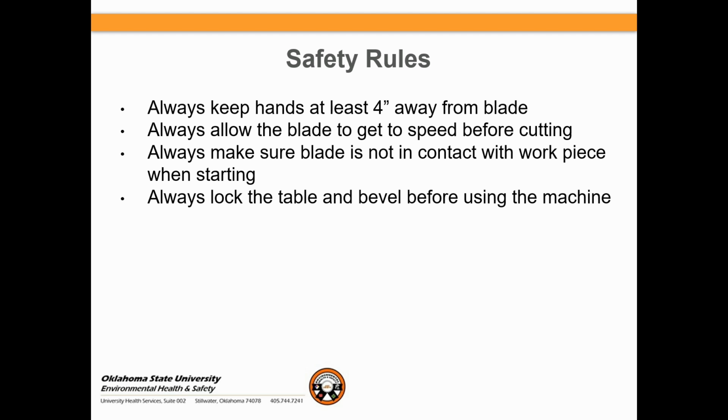Always keep hands at least 4 inches away from the blade. Always allow the blade to get up to speed before cutting. Then just make sure the blade is not in contact with the workpiece when starting. And then two is always lock the table and bevel before using the machine.